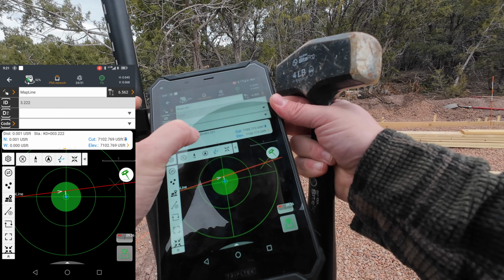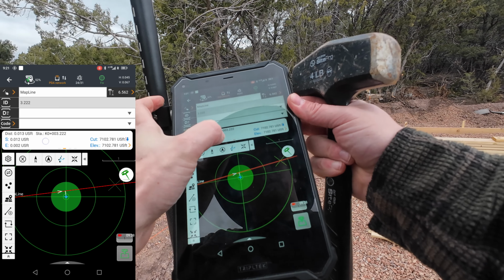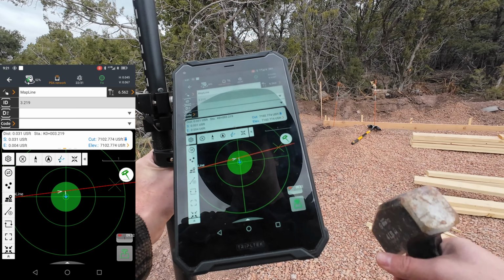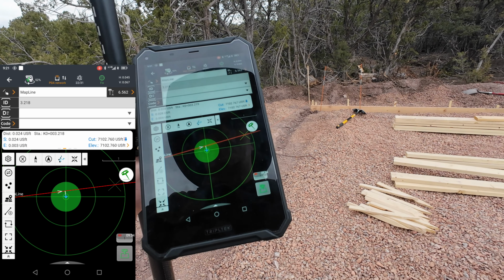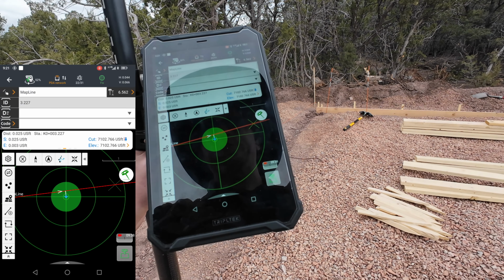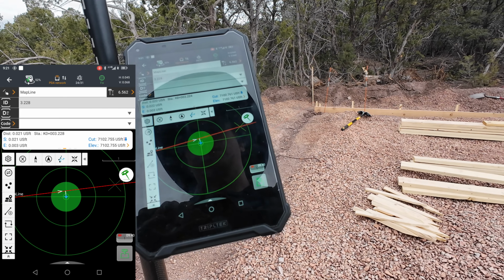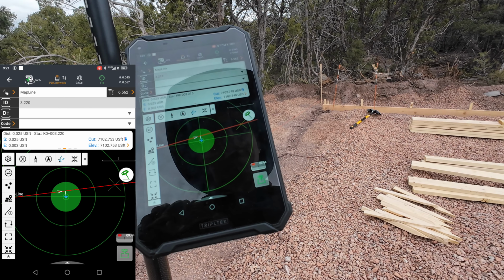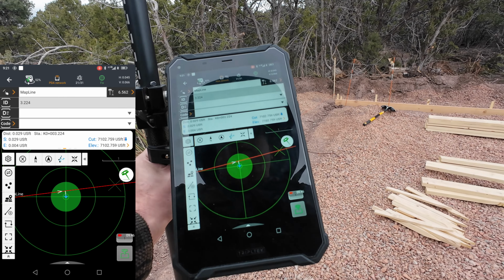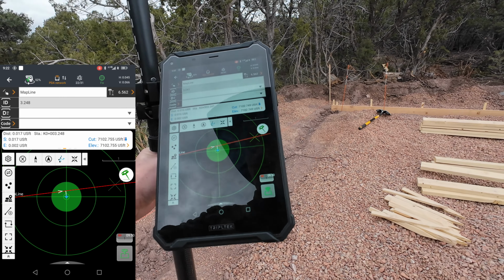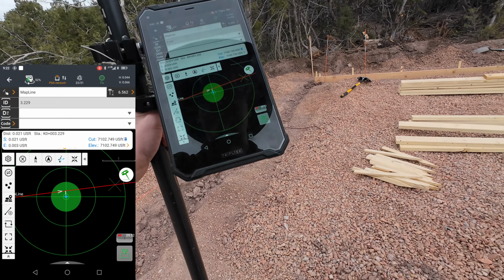And then these values up here are southing and easting. They could be northing and easting. And there's a cut value because this design didn't have any elevation. So the cut is 7,100 feet, which is the elevation that I'm at because the design is at 0. But I am staking to a design line, and I'm staking an offset when I place all of these.